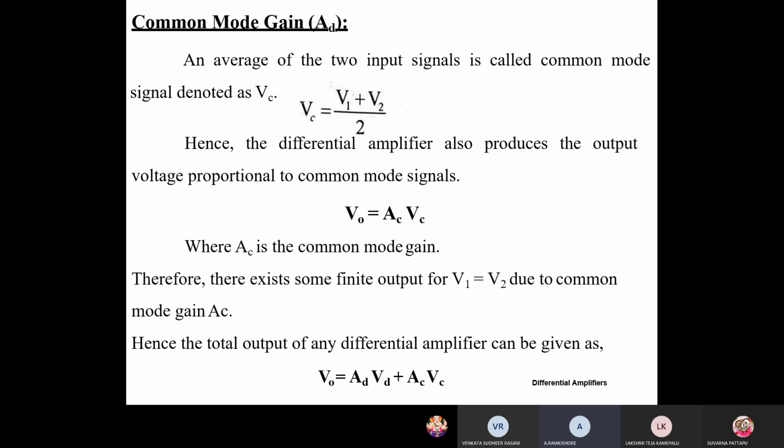So the signals are equal in magnitude and phase when the input is applied to the base of Q1. So the difference output is almost 0, so that the feedback reduces the common mode gain of the differential amplifier.